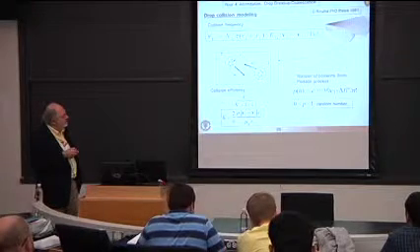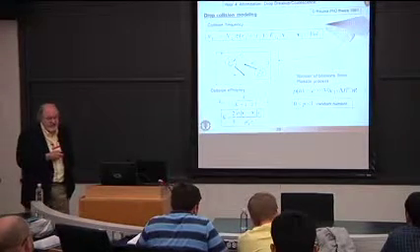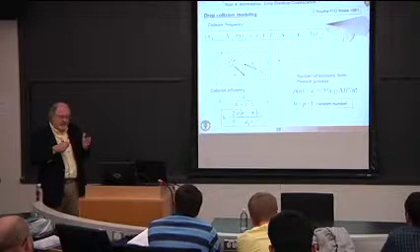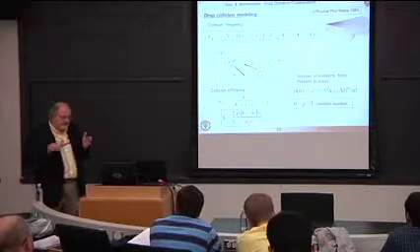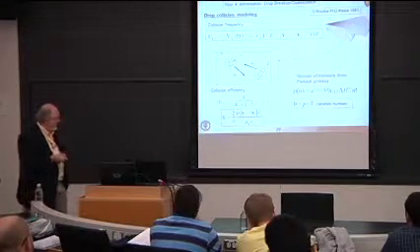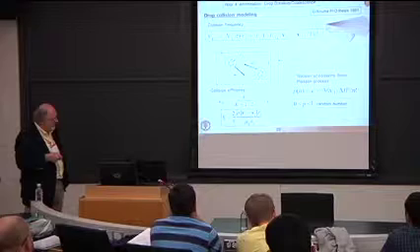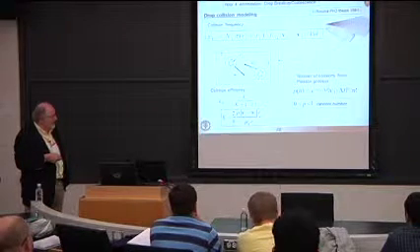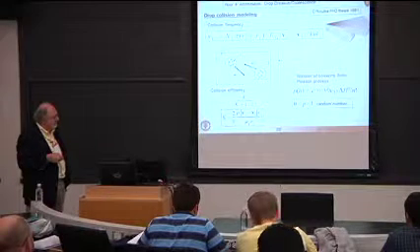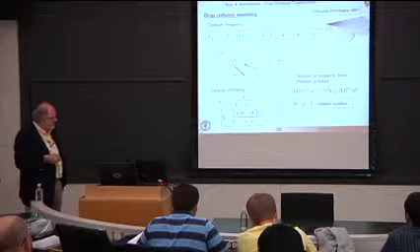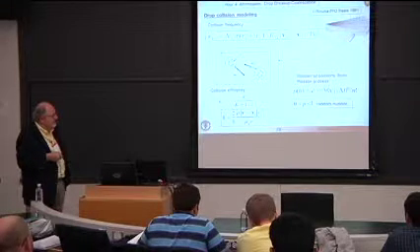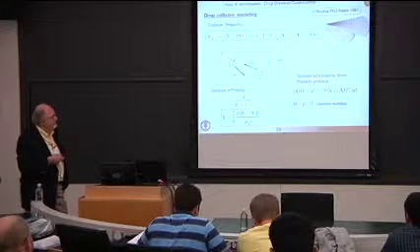I also have this so-called collision efficiency term, which says that if you take, for example, a small droplet and let it approach a larger droplet, it may just bypass that because of fluid mechanic effects. They have to do with this function down here, which involves the gas viscosity. Typically, though, for the droplets of interest in sprays and the gas viscosities that we're interested in, K is large, and so this collision efficiency is taken to be unity.